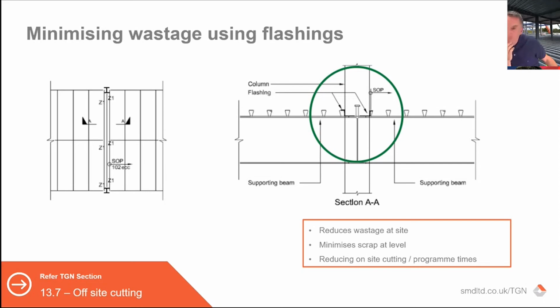So if those are left intact, then you've not got a problem. The issue is when they're damaged. Natural reaction is to stick your finger in and break the bubble. Oh, right, yeah. And if that's the case, then they do need repair. But with an intumescent coating, certainly with our intumescent coatings anyway, if you leave them alone, you're okay. Right, yeah, because you've still got the seal on it as such.